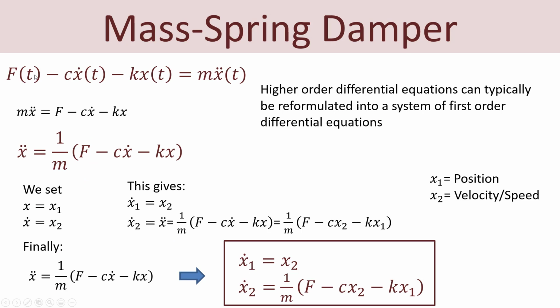So then we have found the differential equation for the mass spring damper system. It's a second order differential equation. Typically we want to have the highest order derivative alone on the left side, so we put the other terms on the right side and divide by m, and then we will have the following system, which is a second order differential equation of the system.